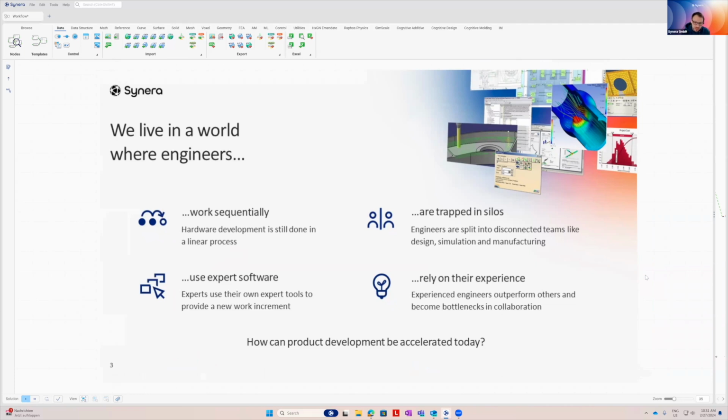When I worked as a young engineer in the FEA department of a company, I learned that a lot of tools are really disconnected, and you have to import and export data from A to B to C. You get data from a customer, different format, then convert it multiple times from STEP to CAD to ANSA to a HyperMesh into a mesh file, and then you set up your solver decks, run them in HPC, get them back, and use a different tool to do post-processing.